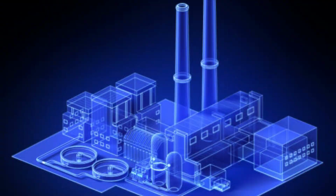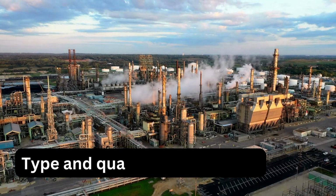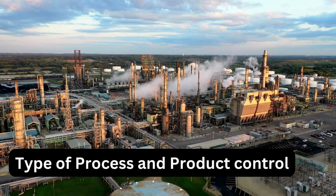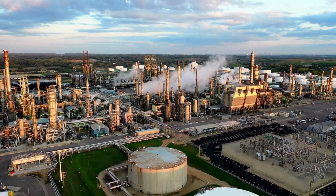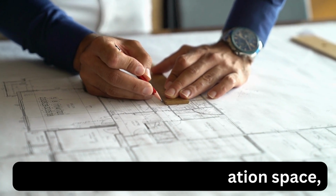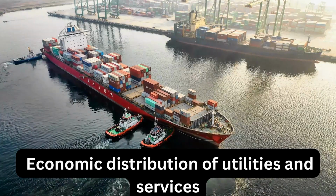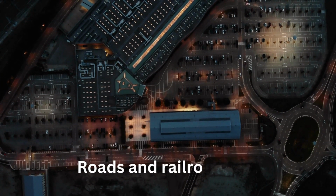Now let's discuss factors to be considered for plant layout. New site development, grassroots, or addition to a previously developed site, which relates to whether the plant is totally new or first time for the business owner or it's an addition to a previously developed site. Type and quantity of products to be produced. Type of process and product control. Operational convenience and accessibility. Sensible use of floor elevation space, space available and space required, type of building requirements, auxiliary equipment. Economic distribution of utilities and services, waste disposal requirements, roads and railroads.